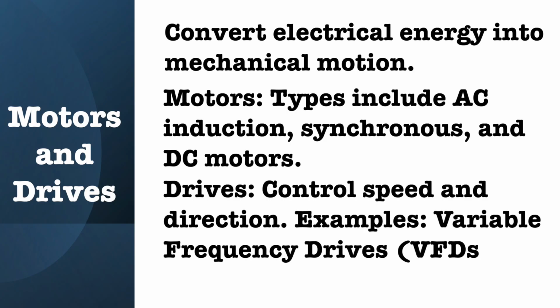Drives include VFDs, that is variable frequency drives, and direct current drives, and play a crucial role in controlling the speed, torque, and direction of the motors. VFDs adjust the frequency and voltage supplied to the motor, enabling precise speed control and energy efficiency. The DC drive regulates the speed of a DC motor by adjusting the voltage and current supplied, making them suitable for applications requiring constant torque across a wide speed range.